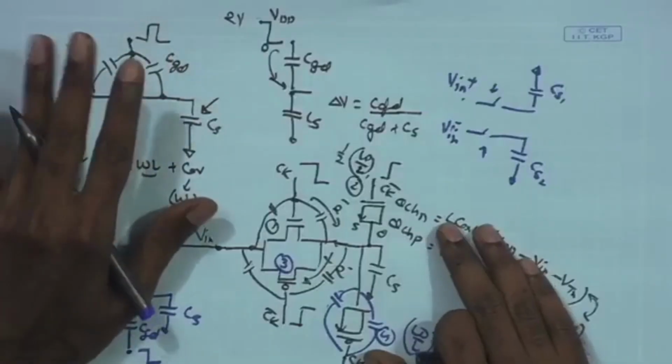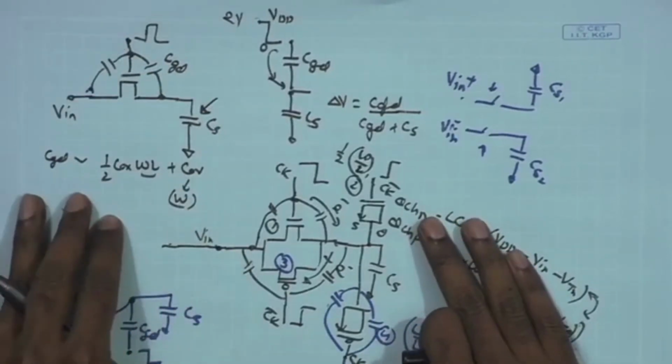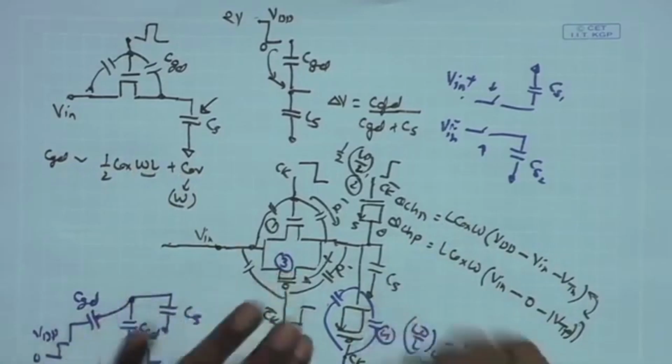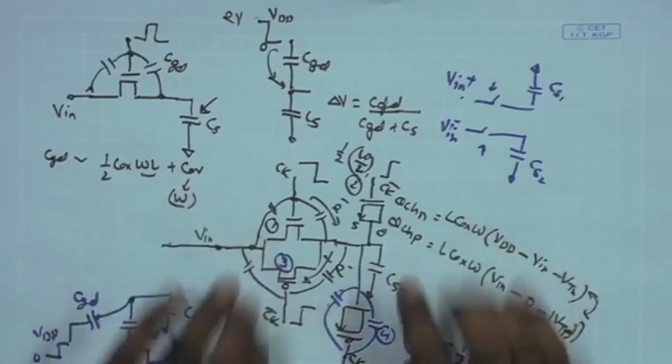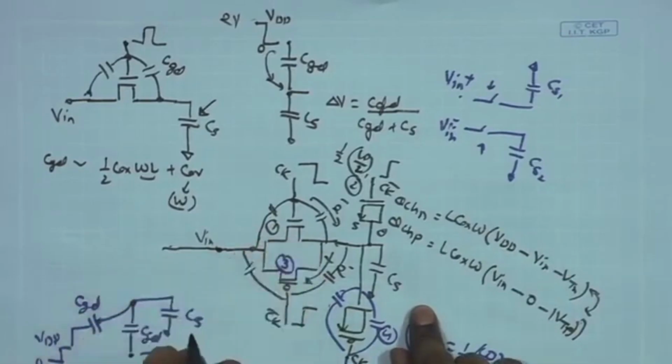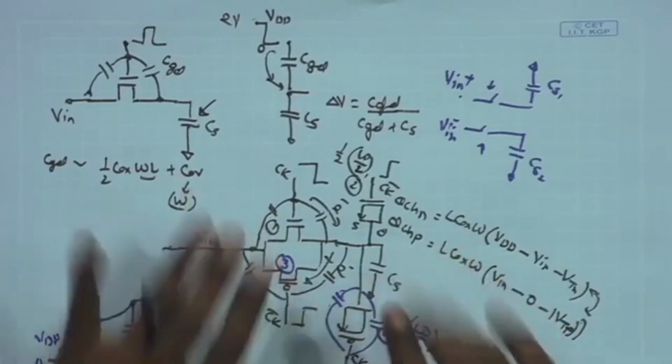Welcome back. So we have just had a discussion on the design sizing of the switches for the sample and hold circuitry, and we looked into the non-idealities associated with the switches, namely the charge injection and clock feed through. There are some other issues also related to the noise of the switch, but here, since we're talking about the ADC and the signal is pretty amplified, we may not really consider the noise produced by the channel current. So we are ignoring the noise part.